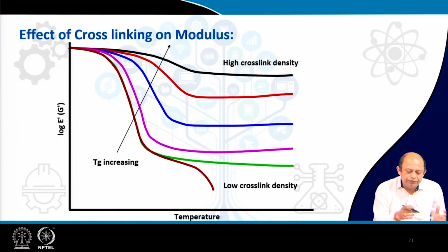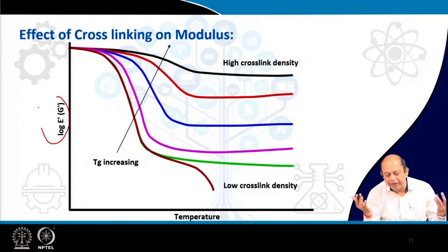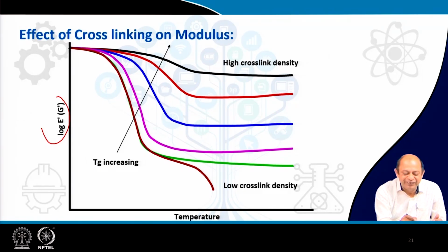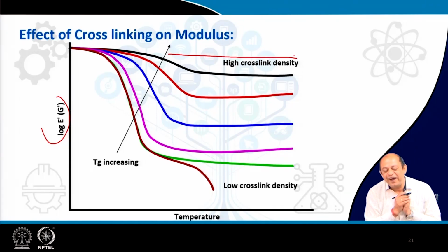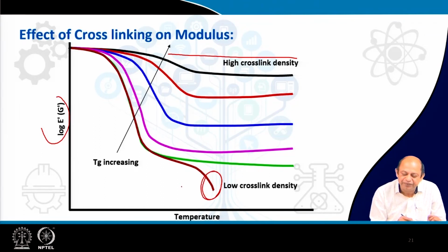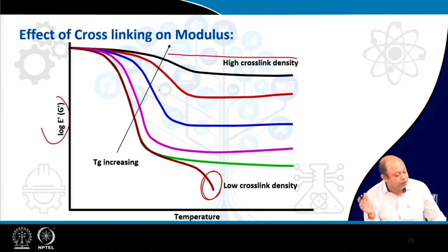If you plot log modulus, you see that if you gradually increase the crosslink density, Tg is increasing. But at some point this plateau will vanish. It will show you what a highly rigid material looks like. So your plateau essentially varies. Initially you have a viscous, flow part, and once you put in the crosslink, it is gone. The plateau gets extended, but if you start putting in more and more crosslink, the modulus goes high, and Tg will also be very broad.